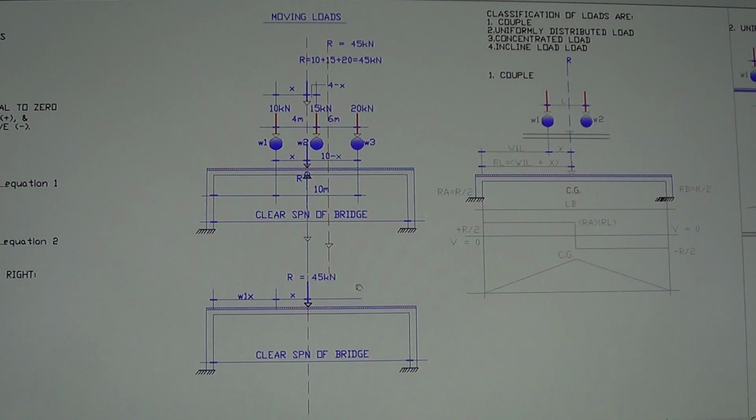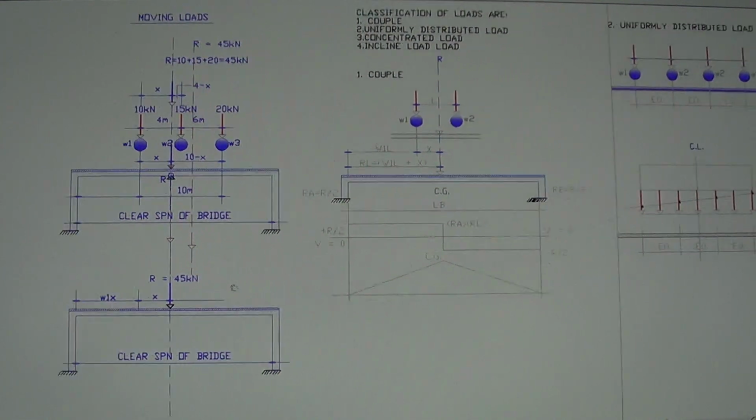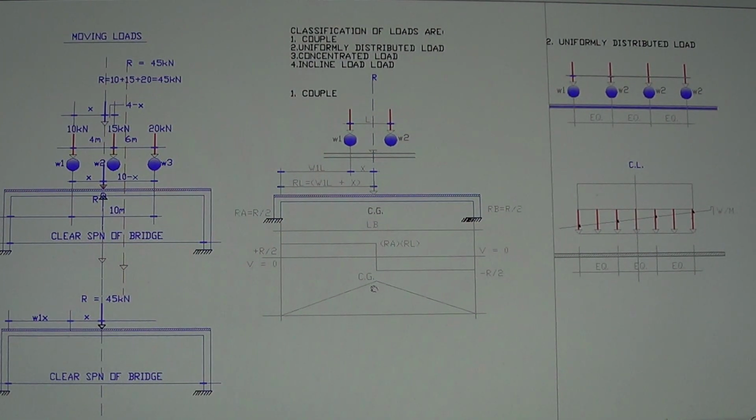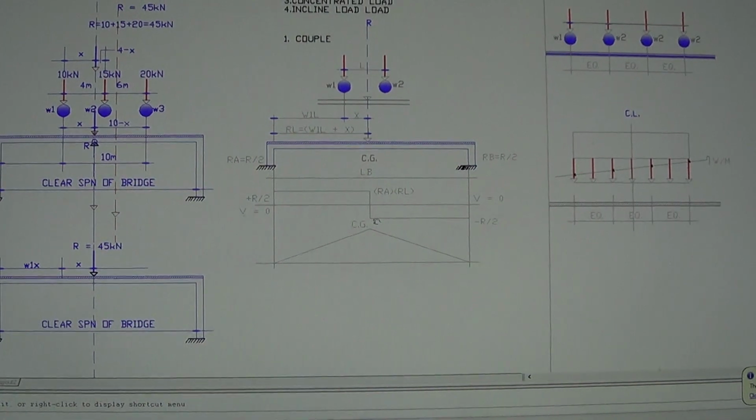So based on the position of the resultant force, you can solve the shear diagram and the moment diagram as well, the maximum moment due to this load. This is just the 2 loads. This is an example, it's the same as this one because of the resultant being 1. This is the layout for the shear diagram, and this is for the moment diagram. The moment here is PL over 4. Alright, so we're gonna derive that later on.